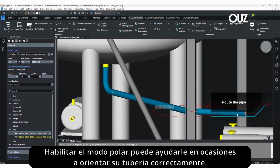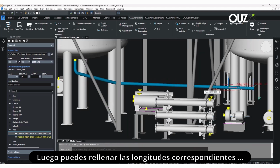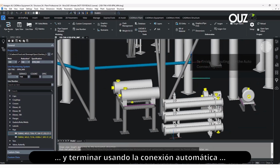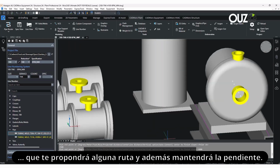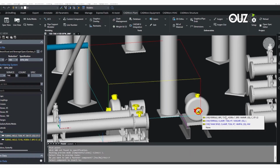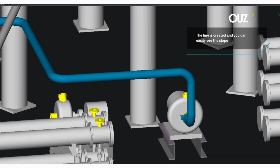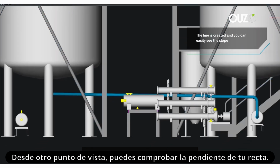Enable the polar mode can help you sometimes to orientate your pipe correctly. Then you can fill the corresponding length and finish by using the auto connect that will propose you some routing and also keep the slope. And here also we will use a clamp connection. From a different point of view, you can check the slope of your line.